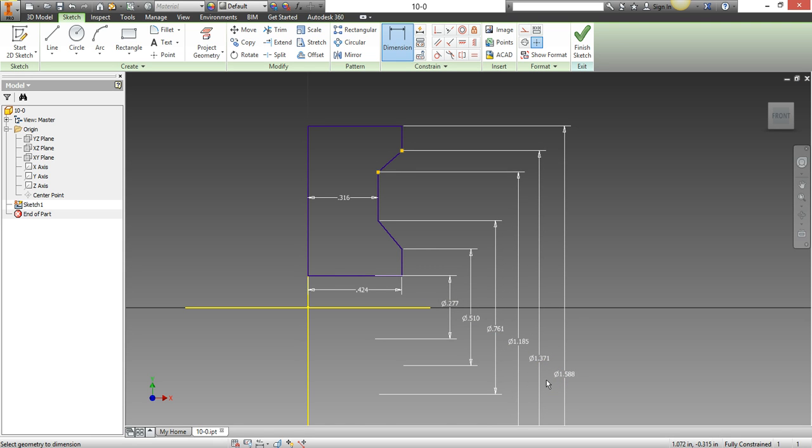It was very, very important, and you probably realized this if you went ahead and did this while it was a good time to pause the video, that if you didn't select the x-axis first, then this did not work as it should have. So one thing really quickly that I know happened for me when I was working on this was this dimension right here. It was telling me that it would over-constrain the drawing because I had this drawn.